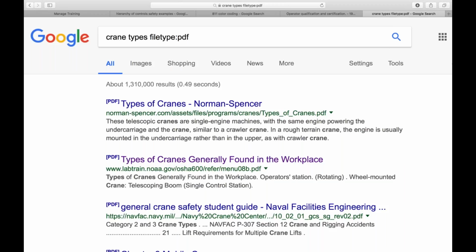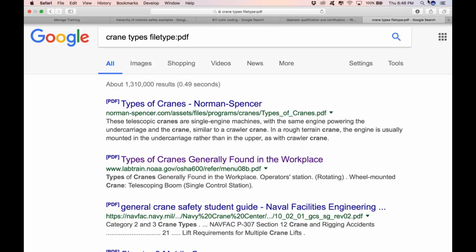So what kind of cranes are going to be there? Who's going to operate them? What type? Are we doing any type of critical lifts, heavy lifts, tandem lifts? What are the requirements for inspections? When's the last time the equipment was certified? Are there any planned use or prohibition of the use of the crane? Suspended personnel baskets: are we allowing personnel baskets being suspended, or are we not? Depends on the job site.